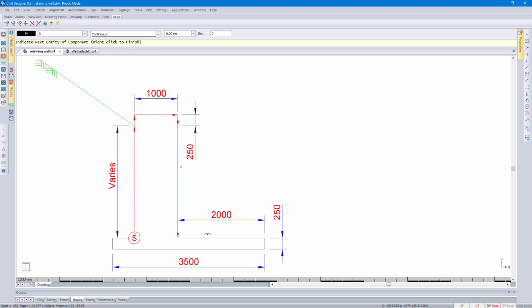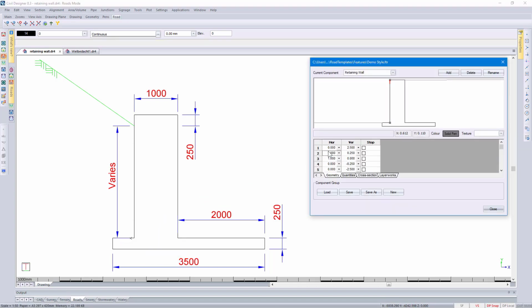Selecting my sides, and then right-click and add. If I now select the different options, you'll see how it's highlighted in my preview. Looking at this first edge over here where I mentioned the dimension will vary, it's a positive value, so I'm going to click on this down arrow and select Extract Next.